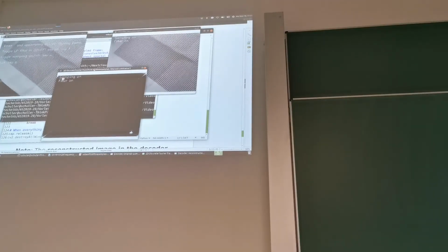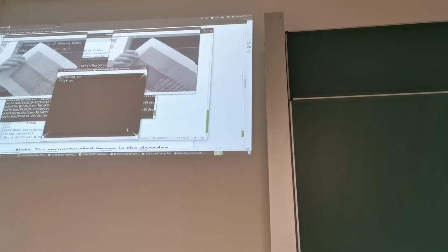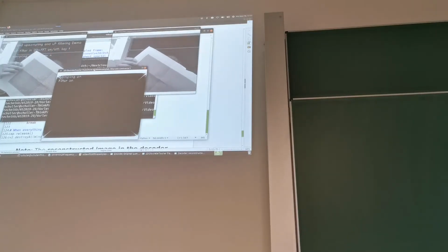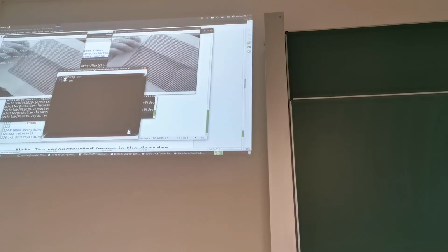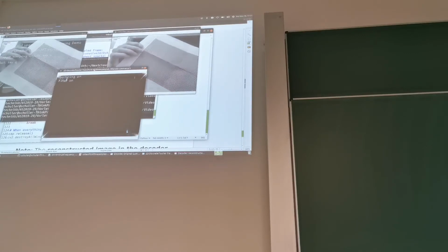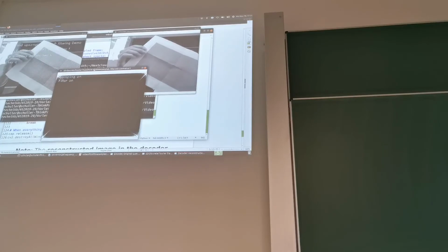But when I'm getting further away, now they disappear because now the low-pass filter prevents those high frequencies. And then the resulting pattern turns into gray in the reconstructed version. So here it's still there, high frequency and reconstructed, you can see it. And now it's disappeared in the frequency domain, and it also disappeared in the reconstructed space domain. It's just gray.